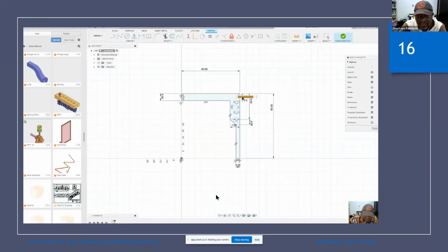So you take your dimensioning tool and you take that distance is 4 units from the top. Okay. And then that arm is also 4 units. So you put 4 there. And then the vertical distance is 2.5. So you pick that and you make it 2.5. Okay. And now you are going to use your constraining tools. Those ones will make it horizontal and vertical.